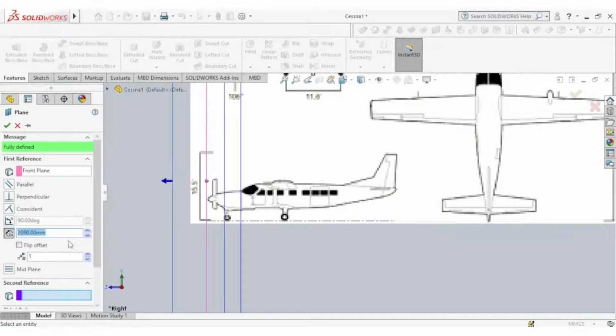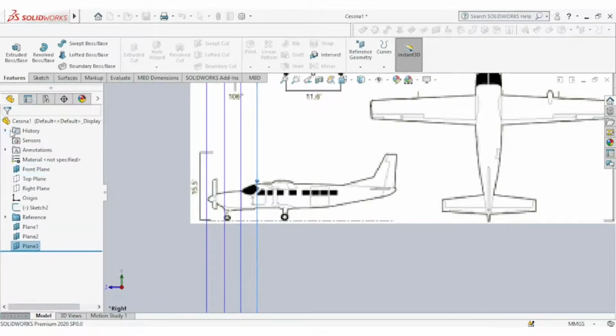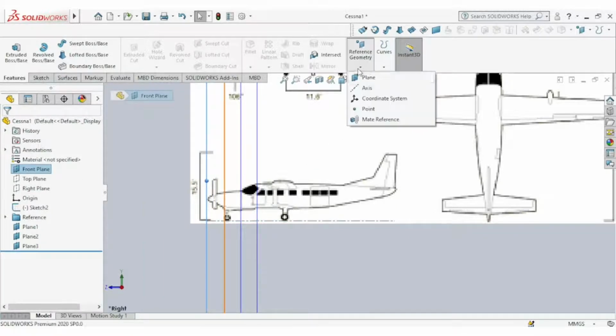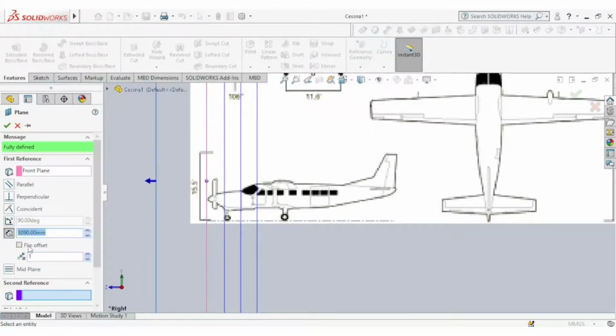The front plane is most often not tampered with, it's always fixed, just like the top and the right. You always just use them for reference points, but in some other planes you can be tempted to modify its location when modeling, and it will bring you problems.